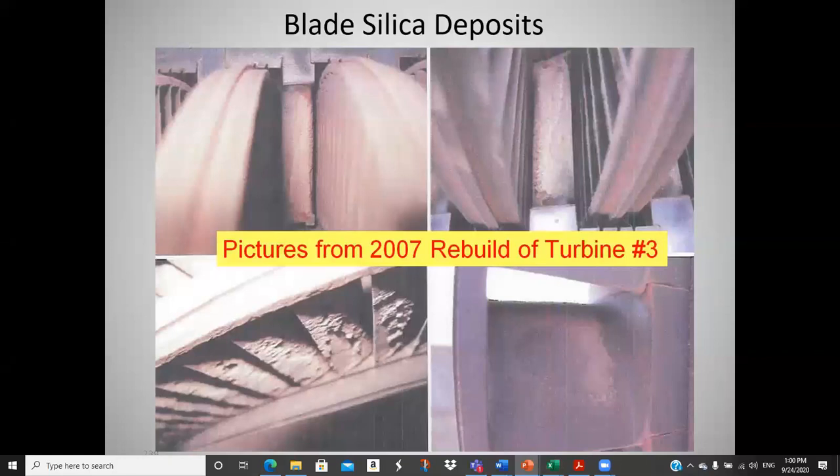So what these guys were doing is a lot of hot water comes out of the process, and they bring that water back, purify it the best they can, and put it in their boiler. But that water comes back loaded with silica, and they couldn't remove all of it. Then they make the steam, and silica is one of the few things that carries over in steam.